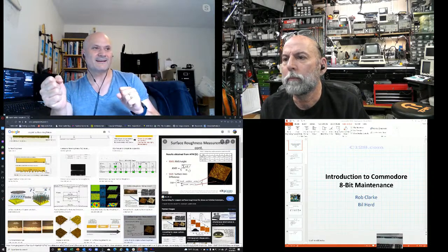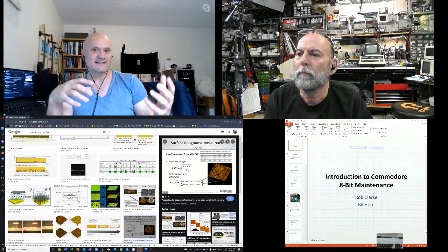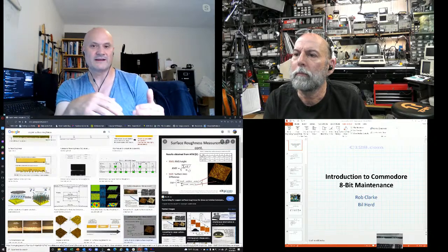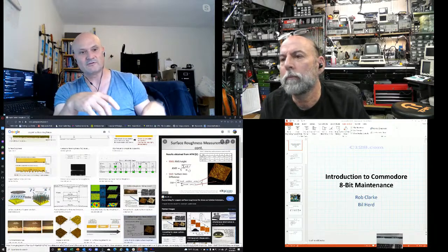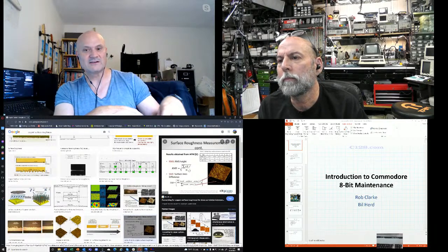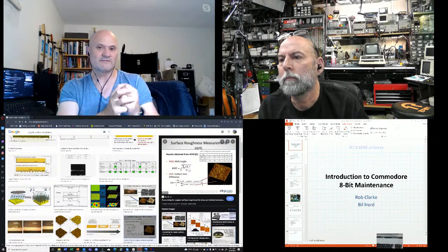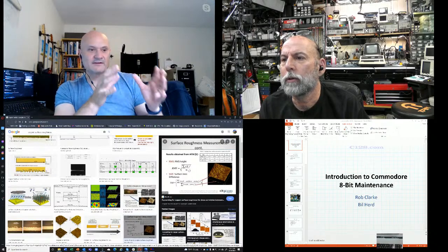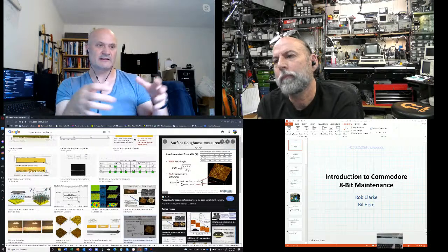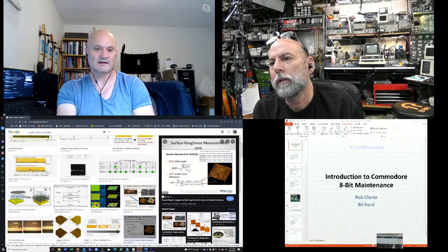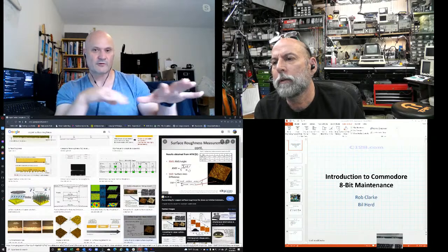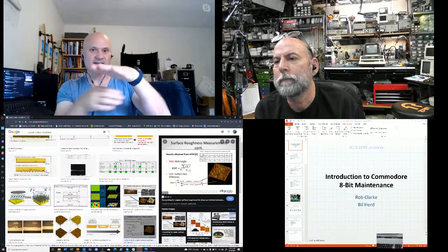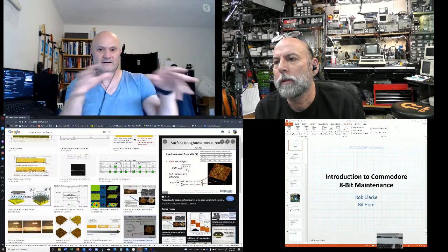But what happens when you have a moving field and a conductor nearby is that the charge inside the conductor has to move to accommodate the field, and vice versa. If you take charge in a conductor and you move the charge, it's going to create moving fields. Right? So in the copper there's electrons, and because it's a conductor, the electrons can move around freely. They're able to move throughout the material. And so as a wave of a signal passes by the conductor, the electrons in it are moving.